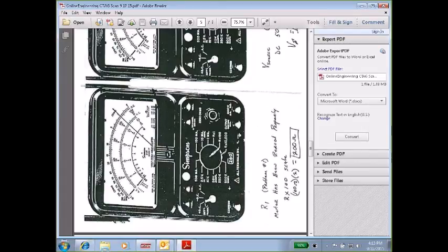Now there is a 0 ohm adjust. Anytime you change resistance scales, you have to re-zero the meter to make sure that it is 0. To zero it, you put the 2 leads together on one of your resistance scales, and that needle should be on 0. If it's not, use the 0 ohm adjust to get it there. Then disconnect it. Also stress with students that you do not use an ohm meter on an energized circuit. It will damage the meter.